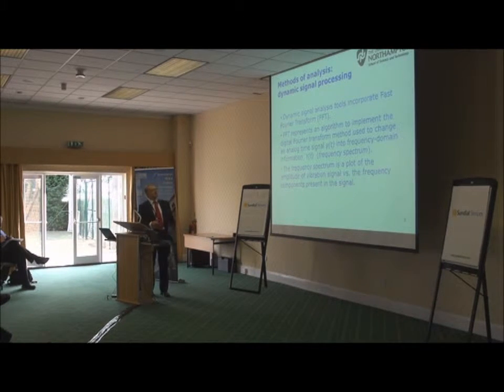Dynamic signal analysis tools include one very important technique, which is the fast Fourier transform. It is a mathematical algorithm which allows us to convert time data into frequency data. And when we have frequency data, we can create the frequency spectrum plot. This is the plot of amplitude of a vibration signal, or any dynamic signal, versus frequency, as opposed to the time domain, when we plot, for example, acceleration against time.